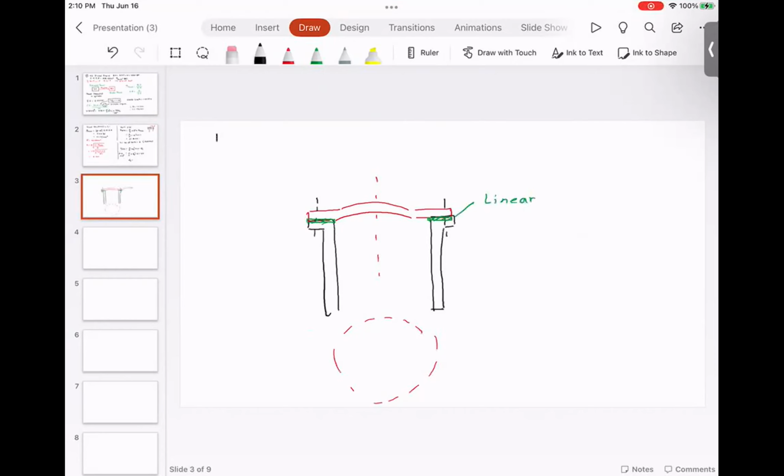The bolts would make sure of the structural integrity, and also it would make sure that the joint is leak proof. So for structural integrity, the number of bolts may be less. But if you want to ensure that the joint is leak proof, then you want to add more bolts.